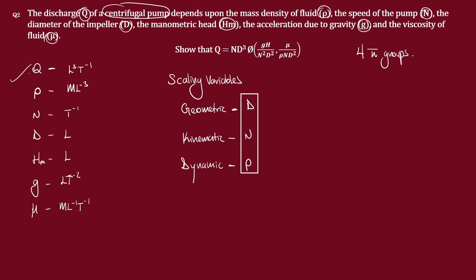It's very important to keep in mind and not lose track of the steps to take when solving Buckingham Pi questions, okay? No matter how big the question is, every problem you're going to encounter is going to use the same steps. List your variables, identify the dimensions, determine the total number of variables, determine the number of independent dimensions, find the number of pi groups, since there's going to be n minus m, then choose your scaling variables.